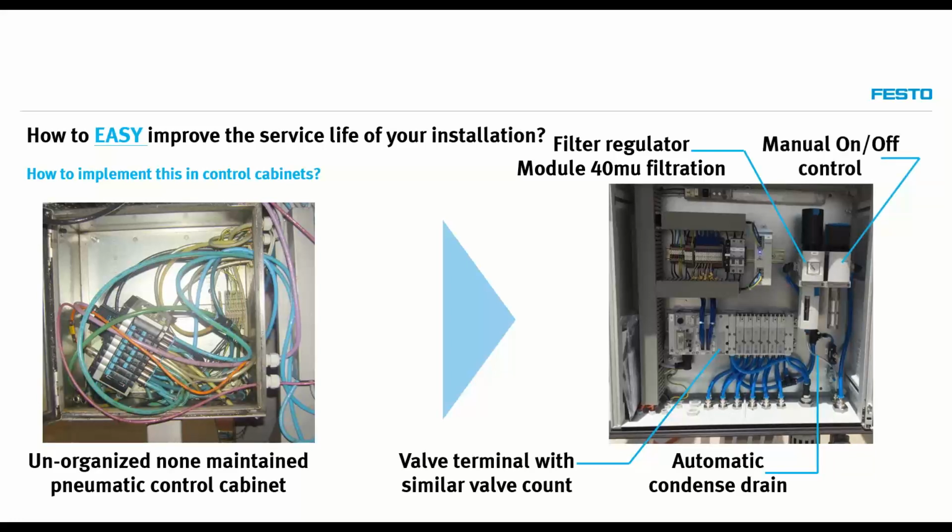Last but not least, we add the manual on-off control valve, again for a safety aspect, to have the operator available to put his lockout tag or key on it, just to ensure that when he's working on the system, nobody else can override it and create dangerous situations.